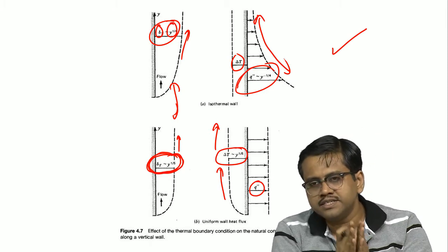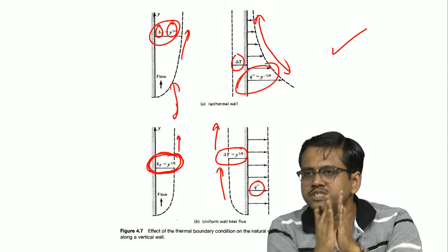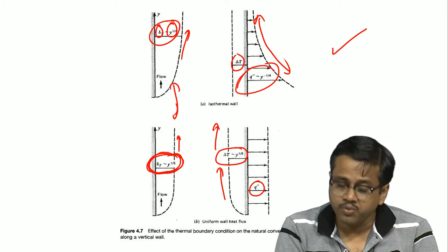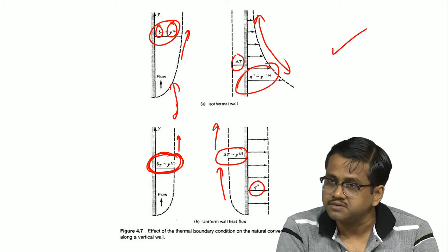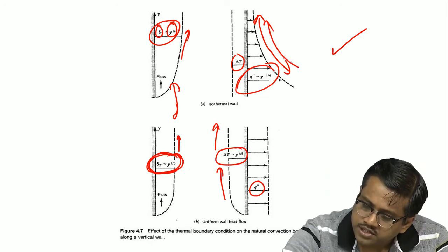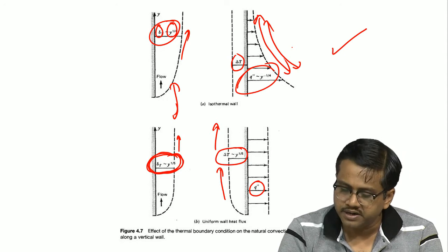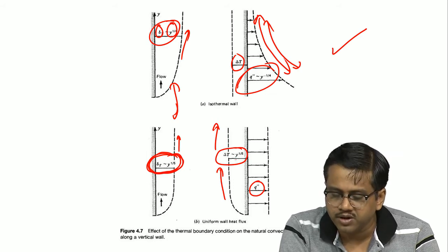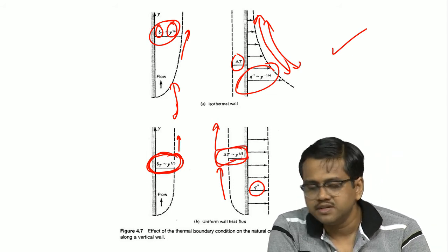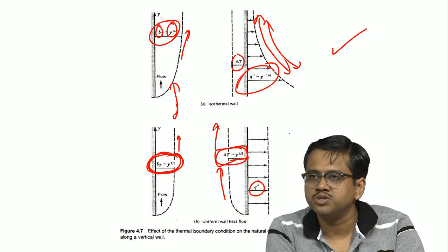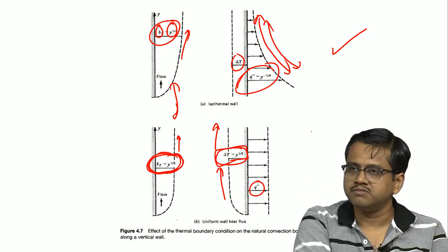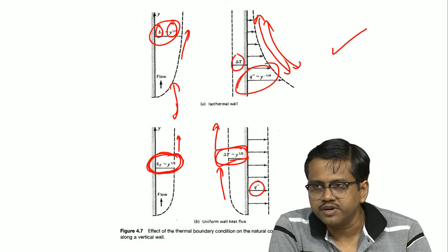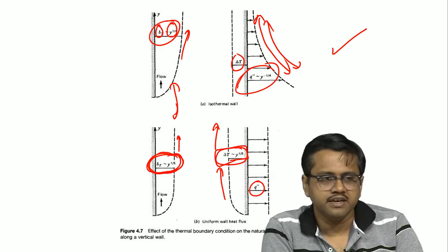So, these boundary layer profiles are almost like constant thickness as they move along the plate, particularly when you deal with the situation of a uniform heat flux. However, the uniform heat flux decays quite rapidly because of the minus 1/4 dependence. The delta T however does not increase that much, it just increases a little bit because of the y to the power of 1/5 dependence. These two dependences are the same. So, these two profiles should also look the same. With appropriate scales, if you place one on top of the other, they will be exactly the same profiles. So, that is exactly what we are seeing in this particular case.